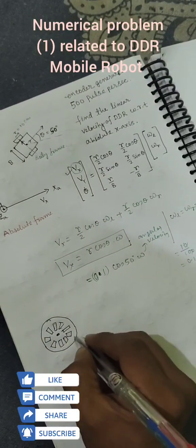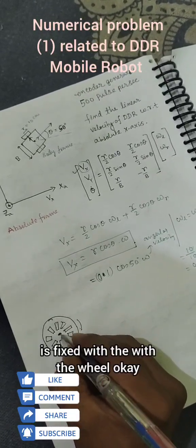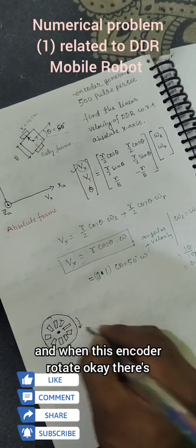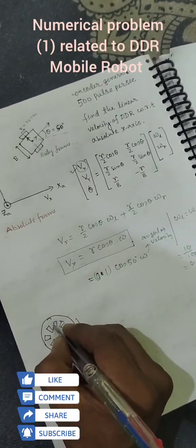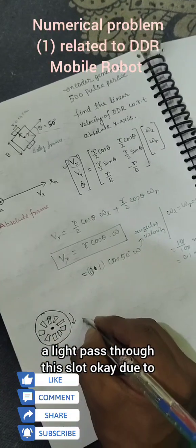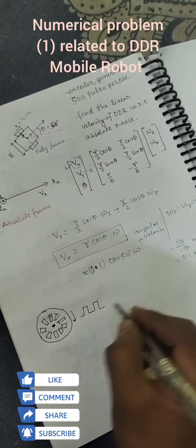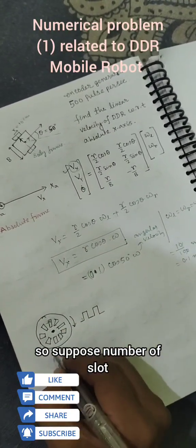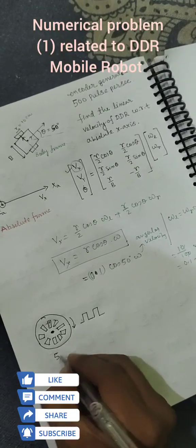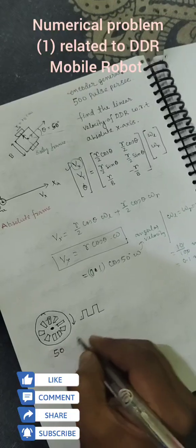Now when this encoder is fixed with the wheel and the encoder rotates, light passes through the slots, and due to that a pulse is generated. Suppose the number of slots is 50.